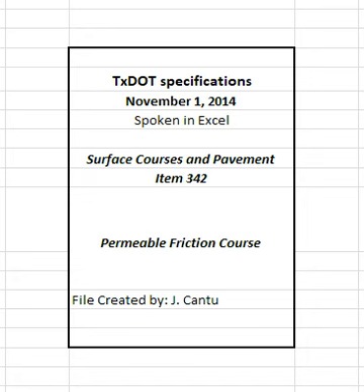When the estimated magnesium sulfate soundness loss is greater than the maximum magnesium sulfate soundness loss specified, the coarse aggregate source will not be allowed for use unless otherwise approved. The engineer will consult the Geotechnical, Soils, and Aggregates Branch of the Construction Division, and additional testing may be required before granting approval. Table 1. Coarse aggregate quality requirements. See table in specifications. 1. Used to estimate the magnesium sulfate soundness loss in accordance with section 342.2.1.1.2, Micro-Deval abrasion. 2. Only applies to crushed gravel.